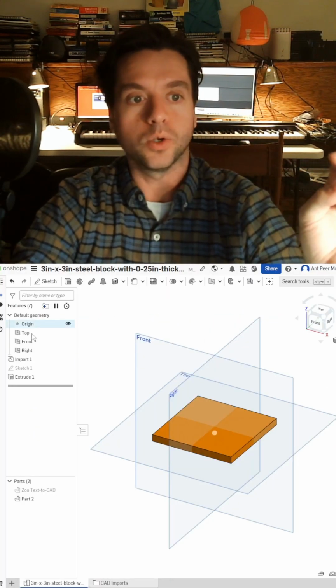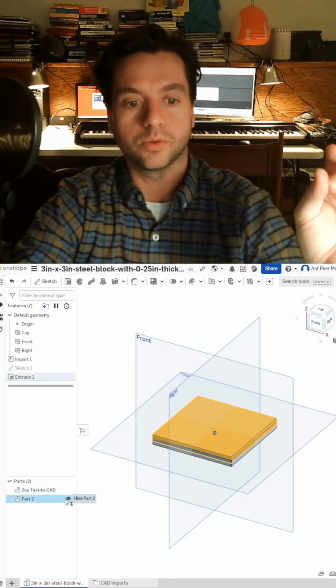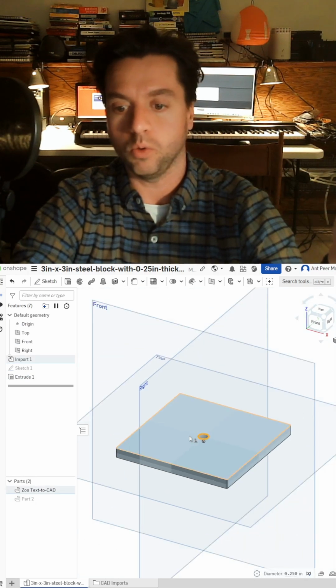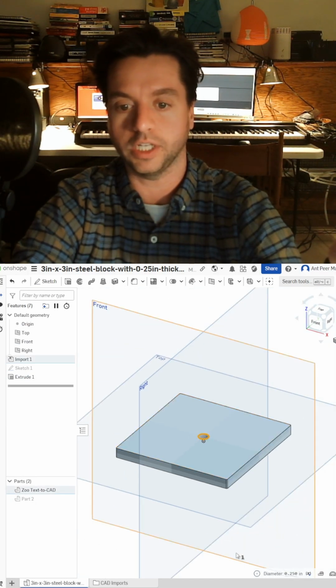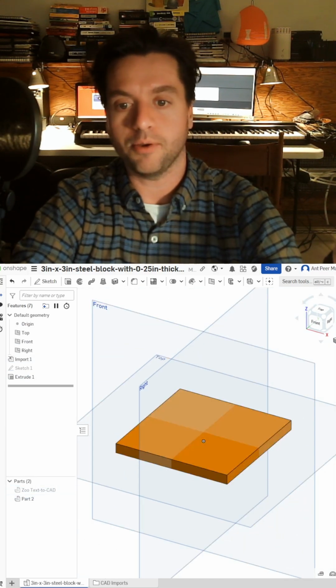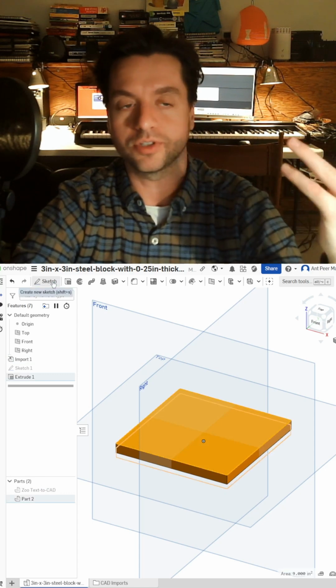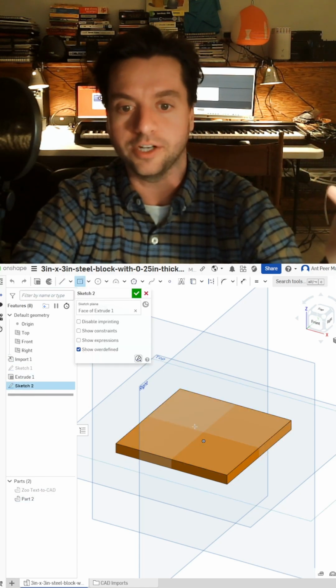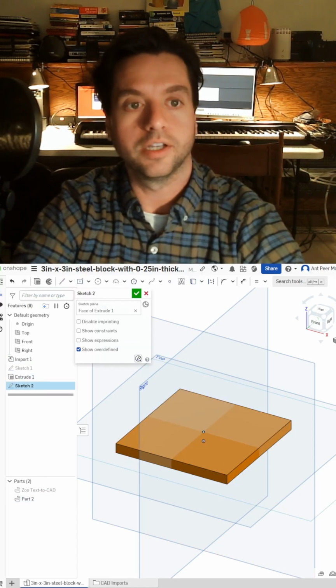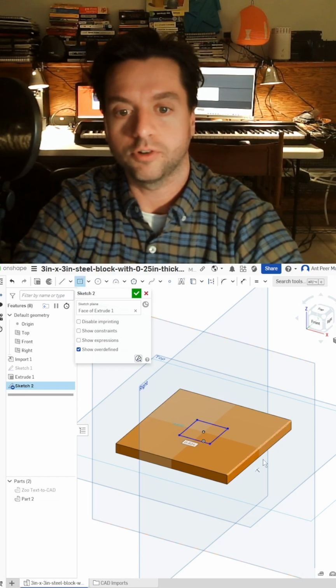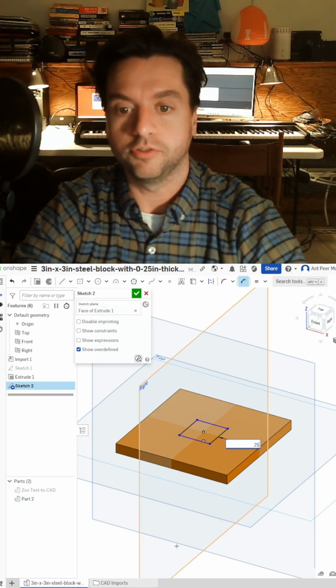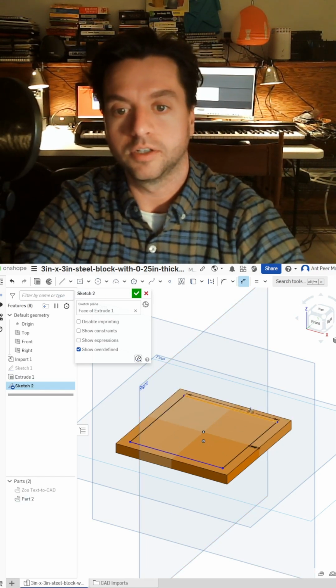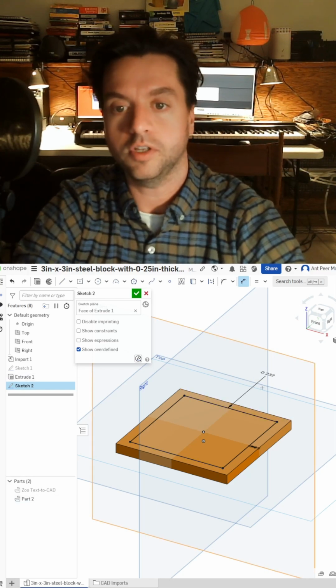All right, so here we have this, a hole made. It's a 1/4-20 hole, right? So 1/4 inch 20, but it's not what I asked for. What I asked for was essentially a hole in the center. Project that, a hole 1/4 inch from the edges, 0.25.